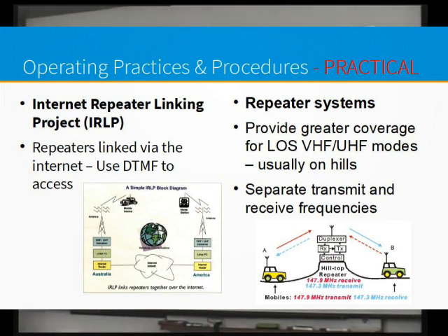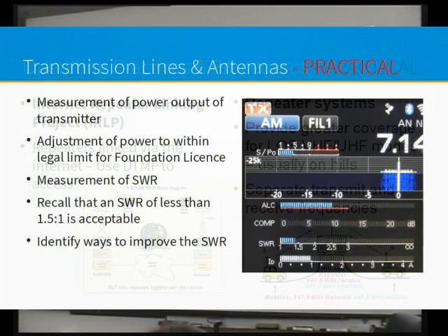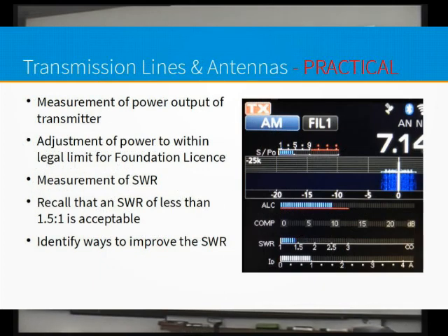Just curious with the repeaters. On the CB band channel 2, there's a funny CW tone. Will that be you guys? No, that's okay. That's a legal requirement. You have to identify. Even a repeater has to identify itself. Every 10 minutes, you find a CW ident, and that'll be the call sign of that particular repeater. Some have CW, so some have Morse code, and some have voice.